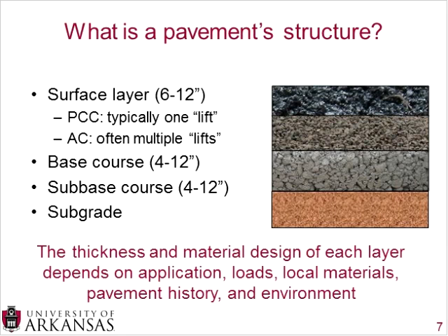And you want to also have a base course for some pavements or a sub-base course. I'll go into more details about the different types of base courses and sub-base courses you have between a PCC and an AC pavement. And of course, these pavement structures all sit on top of the natural subgrade. And the natural subgrade is what is actually sitting in place before you even start building the pavement. And the thickness and material design for each of these layers depends on many, many factors.